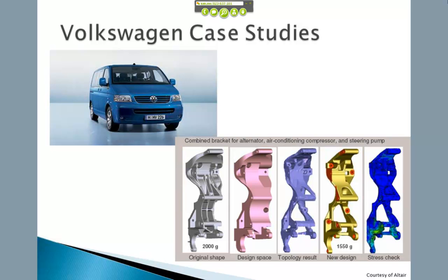And notice the first thing that they brought in, all of these red dots, are what? Their non-design space. They just brought that in from their original design model. Their original model had some size and hole attachment places that they just adopted into their final model. So they brought in the non-design space, and then they began modeling a shape that would be somewhat close to the tessellated optimization shape.